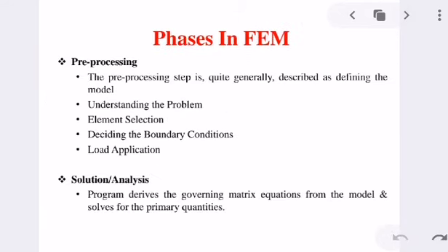Certain steps in formulating a finite element analysis of a physical problem are common to all such analysis, whether it is structural analysis, heat transfer, fluid flow, or some other problems. We can say that there are three phases in FEM. The first phase is pre-processing phase, quite generally described as defining the model, and it includes defining the geometric domain